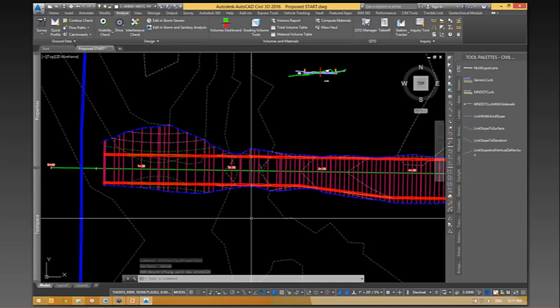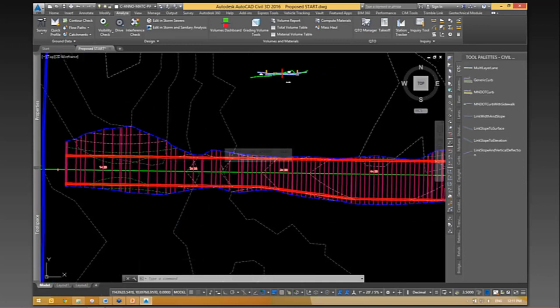And I'm going to create some sample lines. Sample lines are objects that you wouldn't typically print in your construction documents, but they're objects that you need to do one of two things: to generate cross sections or to generate material or earthwork quantities from your corridor.